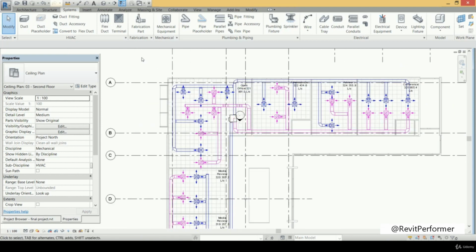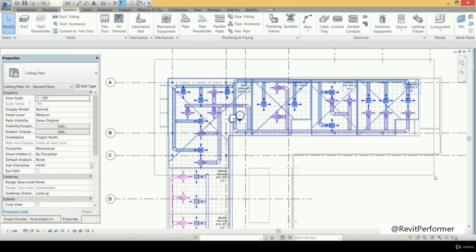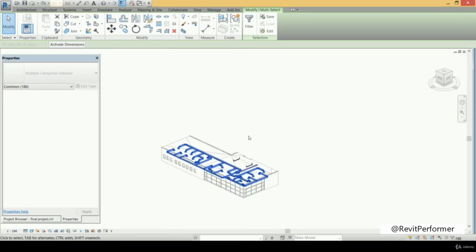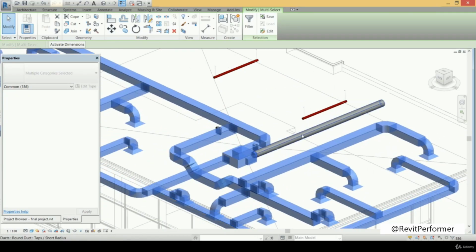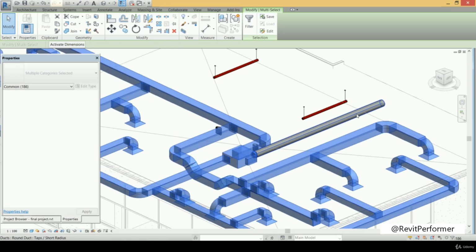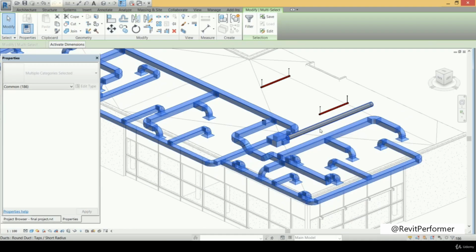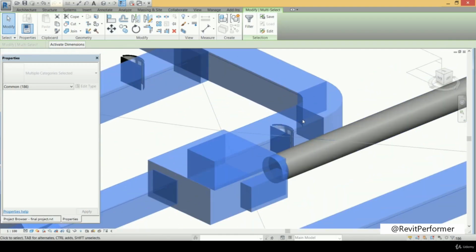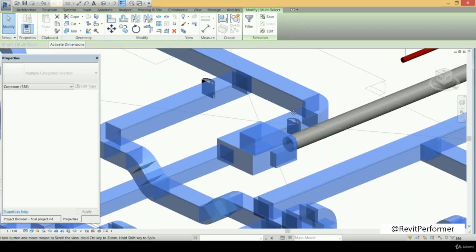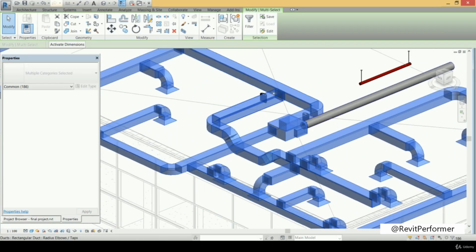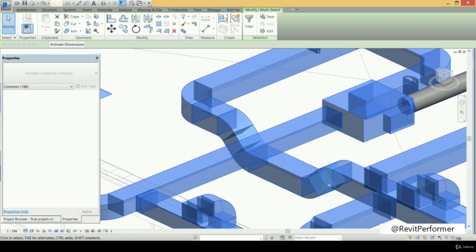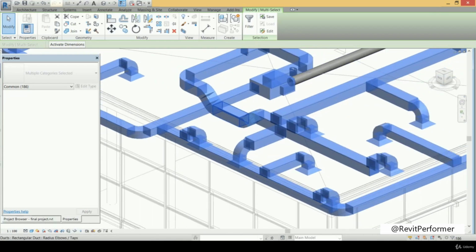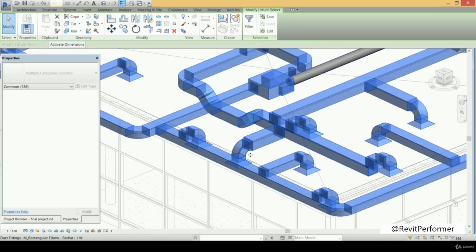And also we can check it in the 3D form. So if I select the zoom here, and then I press on the selection box, you can see this is our system for the supply, and for the return ducts, this is the input duct that is going forward from the main duct from the air handling unit. If you remember, it's going with the supplying air, and then we have that return air duct. So this is the return air duct that we have just created from the previous tutorial, and this is a branch from it, and this is the trick that we have made, which is to change the offset of the return duct to overcome the interference with the supplying duct. And then we go there with that return duct to feed the third terminal and that second one.